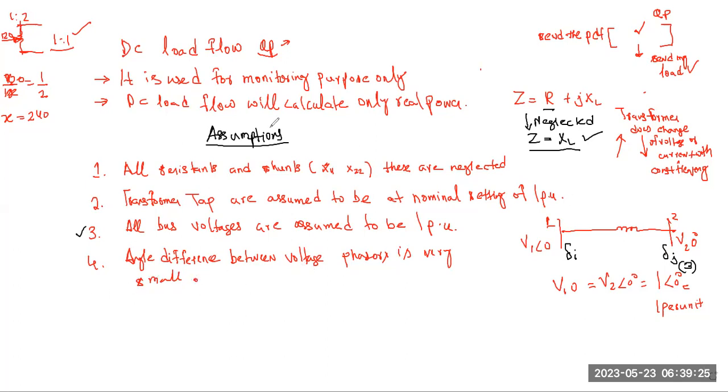Now the final point is that it does not give the accurate value, but it gives you the approximate value of real power. It means you will only be able to calculate the real power approximately, because you are neglecting so many things. Approximate value, because you're neglecting the loss that would be due to R, because there would definitely be I square R loss in the line.